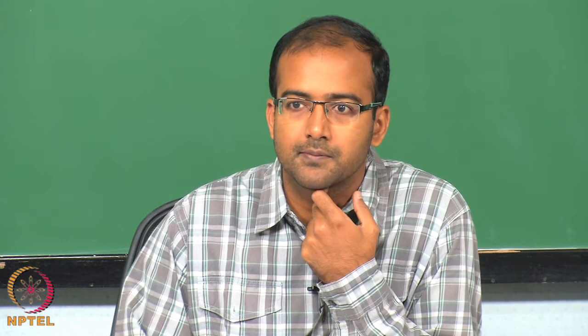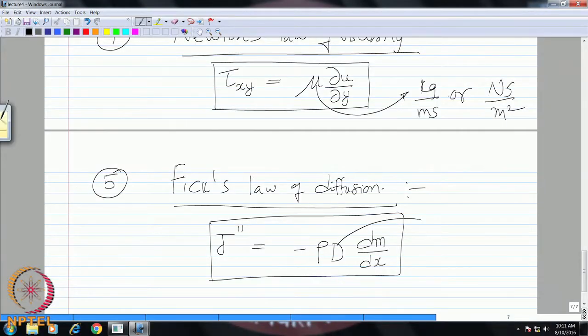Okay. And then you have to use the corresponding diffusivities. In case of Fourier's law, you use the thermal conductivity, and now you should use the mass diffusivity multiplied by rho, so that it is dimensionally consistent. So, here your D is in terms of meter square per second.